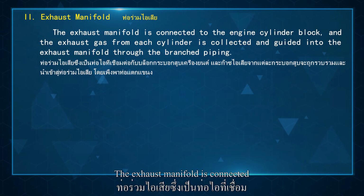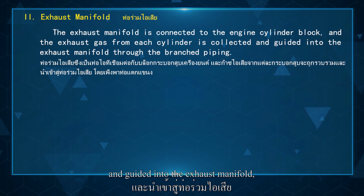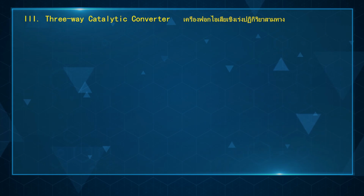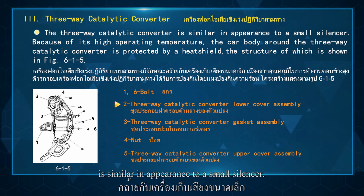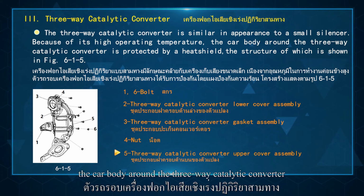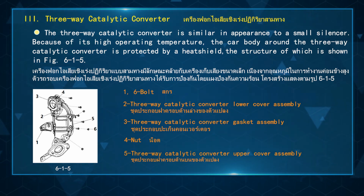The exhaust manifold is connected to the engine cylinder block, and the exhaust gas from each cylinder is collected and guided into the exhaust manifold through the branched piping. 3. Three-way catalytic converter. The three-way catalytic converter is similar in appearance to a small silencer. Because of its high operating temperature, the car body around the three-way catalytic converter is protected by a heat shield, and its structure is shown in figure 6.1.5.